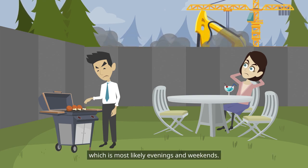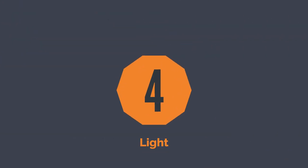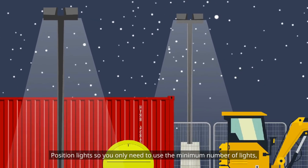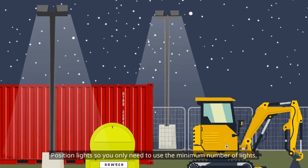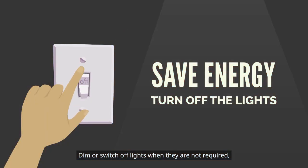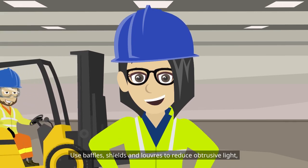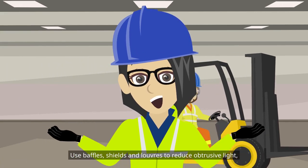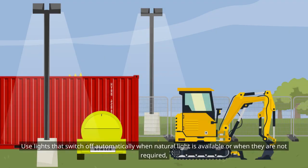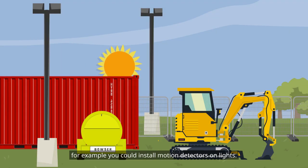Light. To avoid negative impacts from light, you should position lights so you only need to use the minimum number of lights. Dim or switch off lights when they are not required. Use baffles, shields and louvers to reduce obtrusive light. Use lights that switch off automatically when natural light is available or when they are not required. For example, you could install motion detectors on lights.